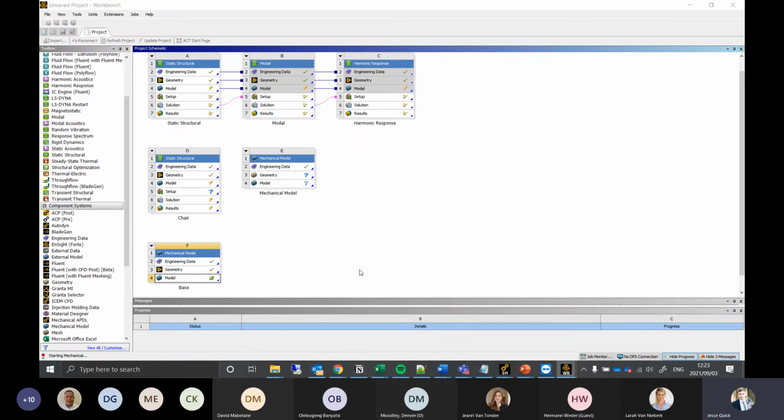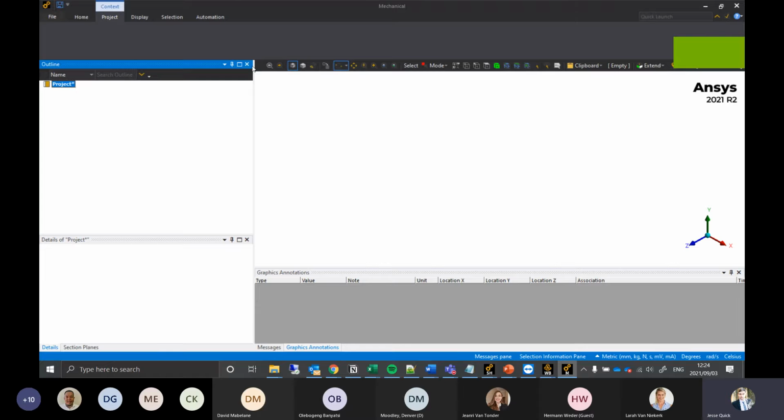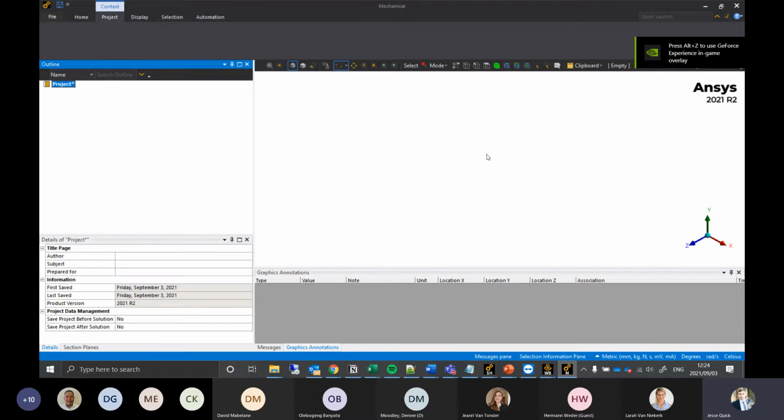Then we can come into our model. And once we go into the model here, these settings that we apply are only going to be applicable to the base geometry that we have defined over there. So that's something important to take note of. Once we've taken it across, we can change it if we want to, but I'd suggest that you don't. Rather come back to this model and edit whatever needs to be changed. Okay, so just as to read it in.